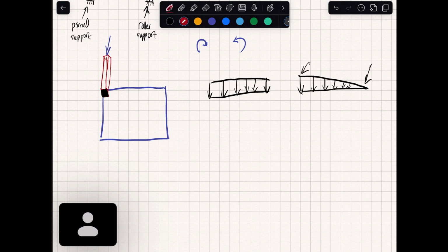And what can this be? This can, for example, be if you have a wall here, and the wall is carrying load from the roof. And this wall is throughout the entire length of the slab. So in that case, you will have load that is distributed along here. And the same way, you can also have an area load, which is also a type of distributed load. So you can have a load distributed over an entire area, which could, for example, be furniture load or even dead load. For example, the dead load of the slab.